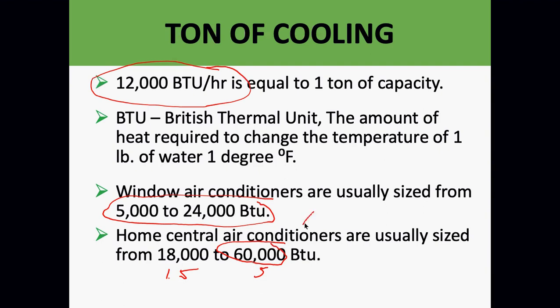But now let's talk about ductwork. What's the size of ductwork going to be like that I have coming out of anything over 5 tons? It's going to be pretty high, isn't it? It's going to be pretty large ductwork to get that airflow movement. Might I not want to go that heavy on ductwork? Might I want to use smaller ductwork so I can get through the attics, the crawl spaces, and everything? Sure.